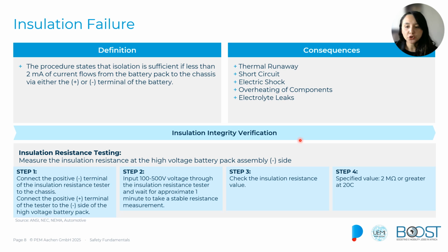So in order to prevent insulation failures, we have some recommendations. The first one is always to check whether the systems we are working on have any visible damage, cracks, or signs of wear in the components. Also, we have to keep the equipment and the system dry and protected from extreme environmental conditions. And we also have to work with insulated tools and protected materials.